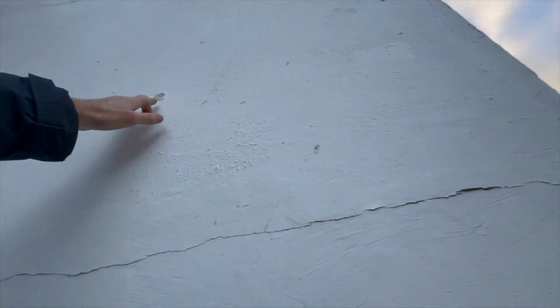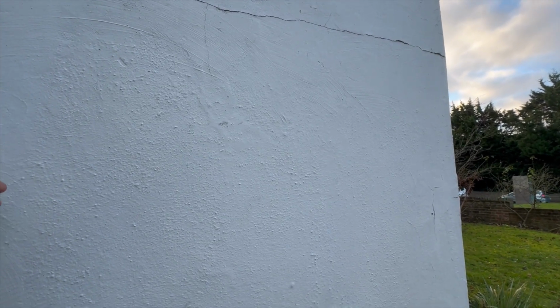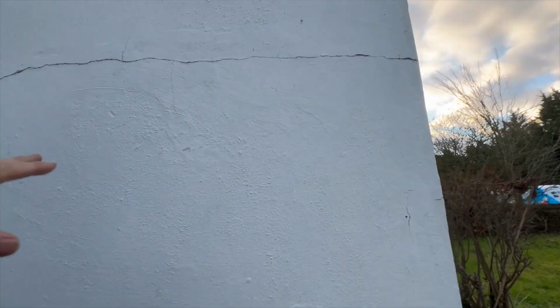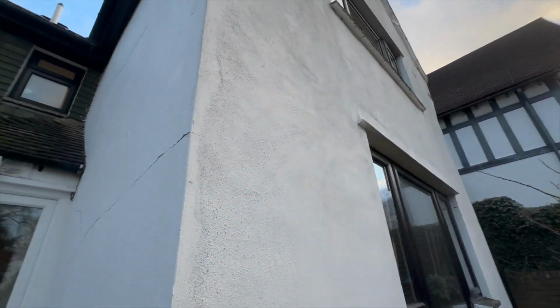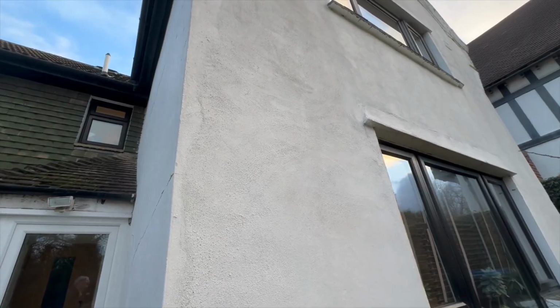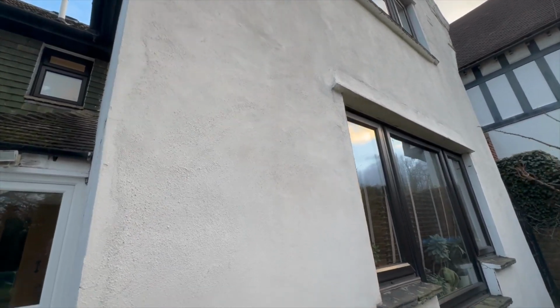We can see with these dots here that there's been cavity wall insulation, so generally that isn't a problem, but if water gets through the render, then it will dampen the cavity wall insulation, which will actually be counterproductive. But I'm not seeing dampness and mould on this side of the property. It's on the front, and actually the front is south facing, I believe. Oh no, sorry, the front is north facing. So that's why it's colder.